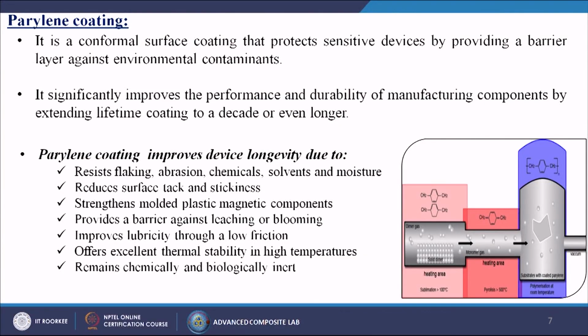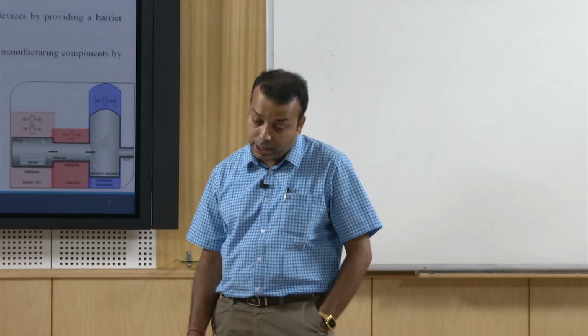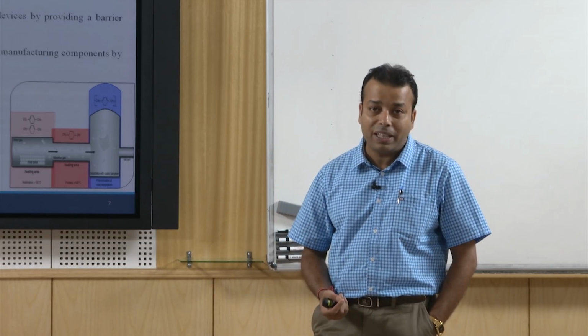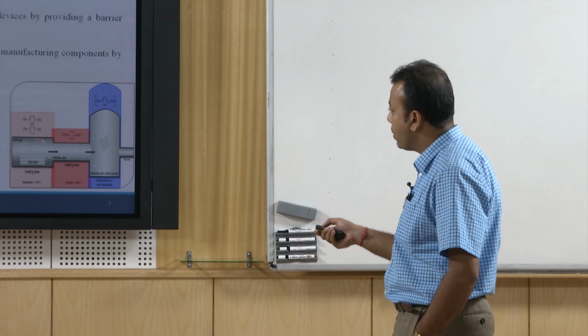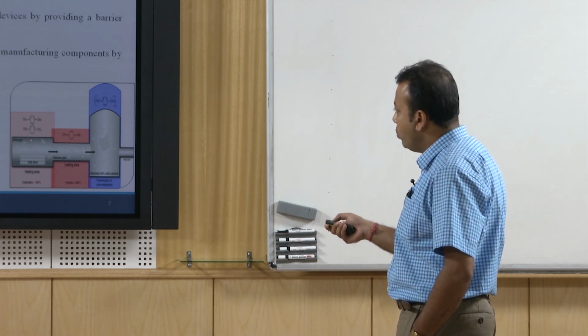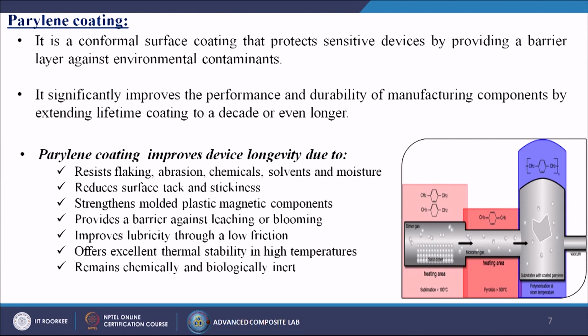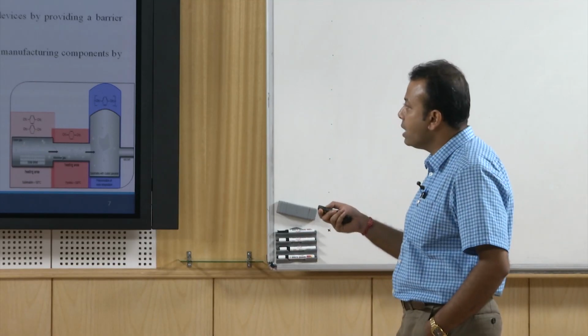So, Parylene coating is also one kind of chemical modification method, by which we are trying to do some kind of chemical reaction. We have a substrate known as the solid dimer, and we take gas molecules, or some inert gas, and do some chemical reactions between them so that a gas is generated. That gas comes directly through the chamber and coats your materials. By doing this method, we call it a Parylene coating.